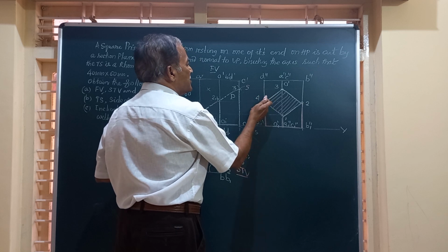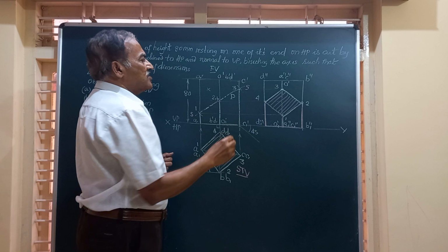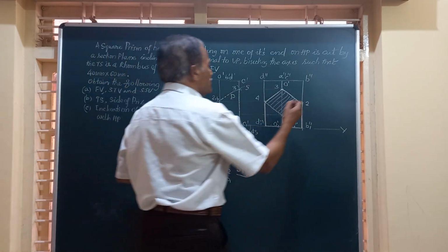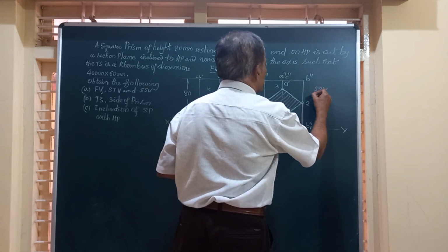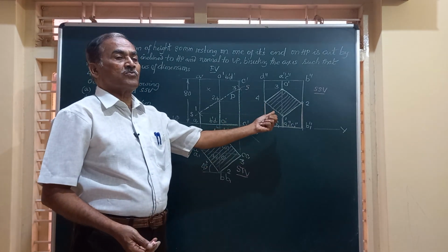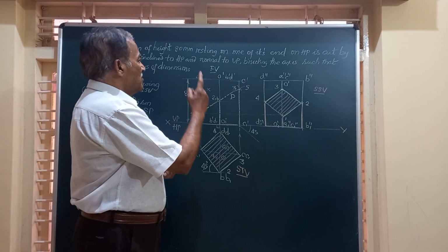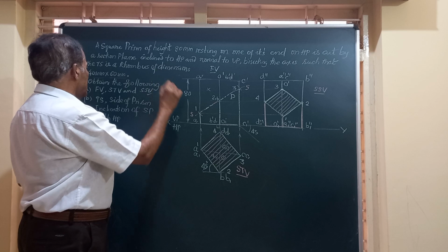And friends, the portion above this, these lines are to be shown by very thin lines. So friends, this will give you the sectional end view or sectional side view, or left sectional end view, because this is obtained on the right profile plane. Friends, you got the front view, you got the sectional top view, you got the sectional side view.